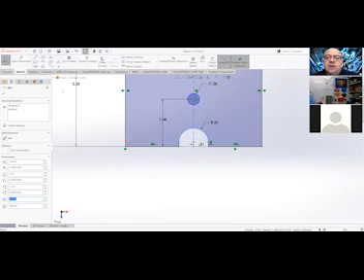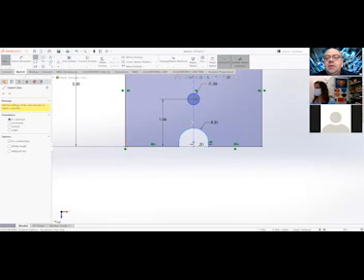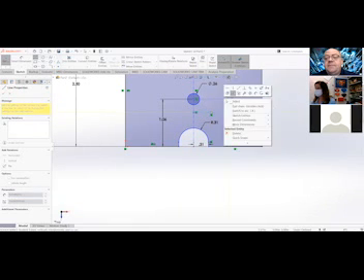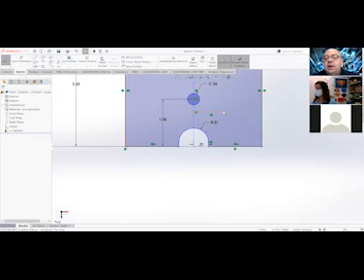This is why we have center lines. And so if you mess up, there's so many ways to fix it. I'm gonna take a center line. I'm gonna start on the center line and just draw a horizontal line. Just like that, okay? Now, that's pretty easy. And notice it ties. Now this constraint right here looks kind of like a perpendicular, but it's really a knot. So it's where two things are tied together.